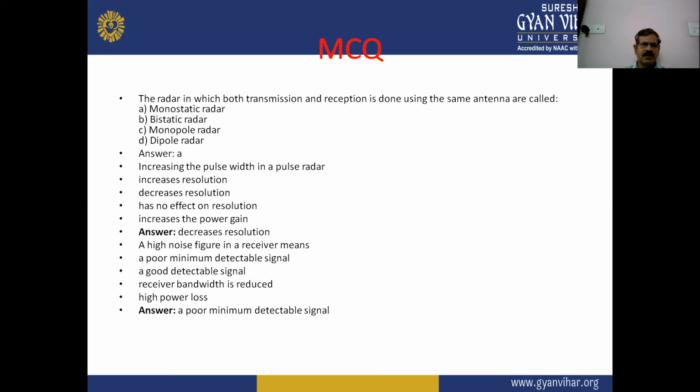So the correct answer is decrease resolution. That is answer B. If we increase the pulse width in a pulse radar, in that case it decreases resolution. So this is the correct answer.